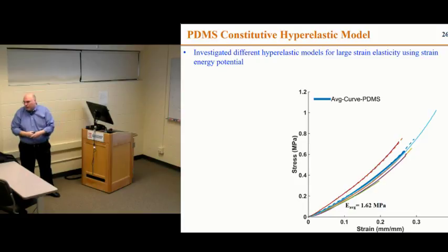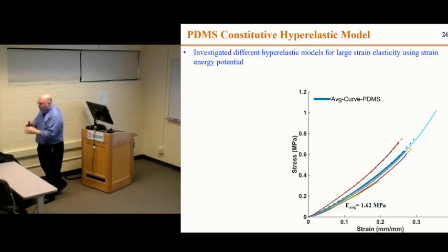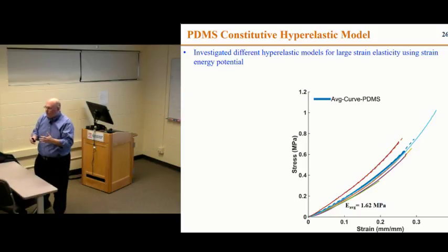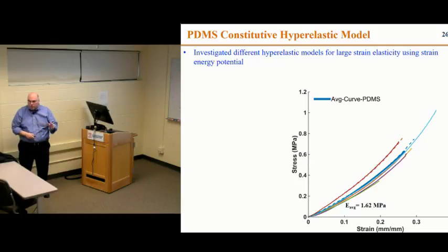So this we studied numerically with collaborations with a group at Imperial College whose background is in the study of PBX and HMX explosives. So first we started by determining a model for the matrix. One thing that I haven't told you so far is that there is a bit of scatter in these results, right? So not every experiment is identical. There's a little bit of a spread. This is kind of representative of a spread of the stress strain response of just the matrix on its own. So no marker particles, no reinforcement, nothing.